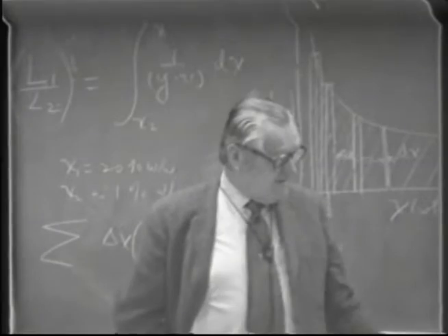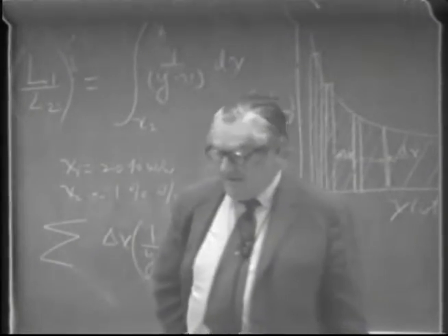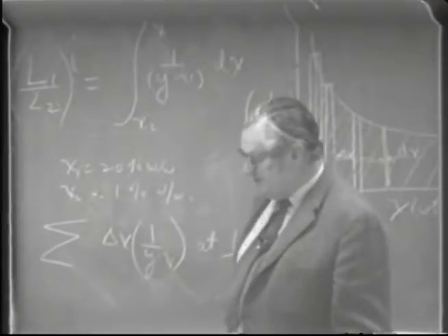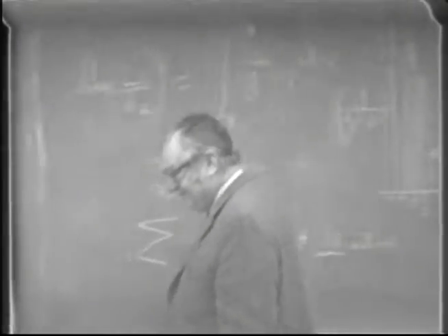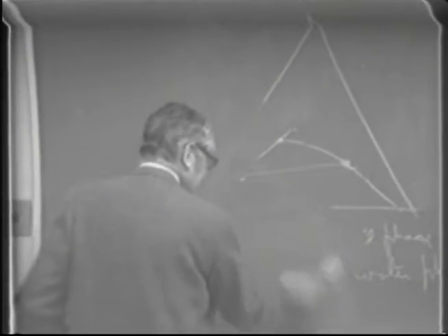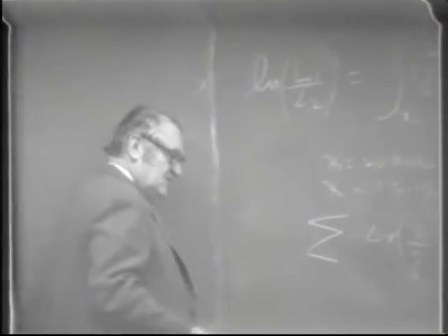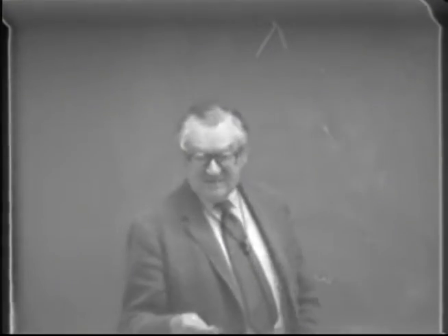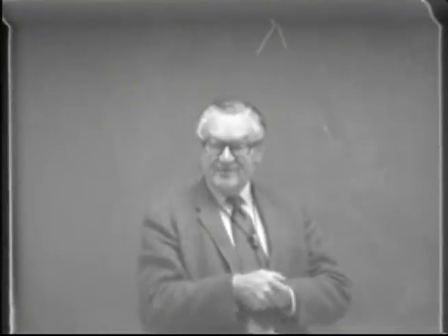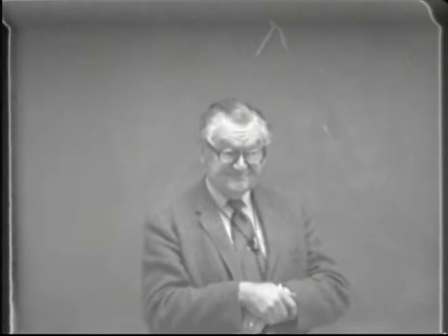Well, the temperature break is simply that region in the column where the temperature changes very rapidly, and that's simply in the region of the boiling point composition diagram, where you're getting maximum change in concentration from very low alcohol up to very high alcohol, or relatively high alcohol, in just a few trays. And of course the temperature changes very markedly.